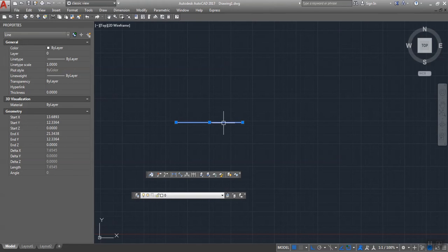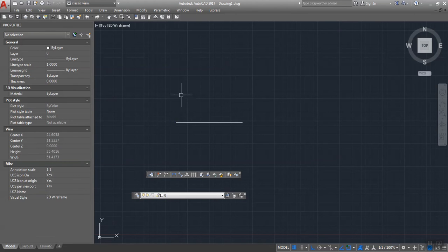And as I selected the layer, you can see that it's been selected. It has 3 nodes, which is typical for any object that you create in AutoCAD. As you see down below under the geometry subsection, you'll see the location, the coordinates of the line, where it is set in the whole model space. And then down below you also have no angles, but you also have the length. The length is also shown. That's how long this line is. So when you deselect it, you can see it goes back to normal, and you can delete it.